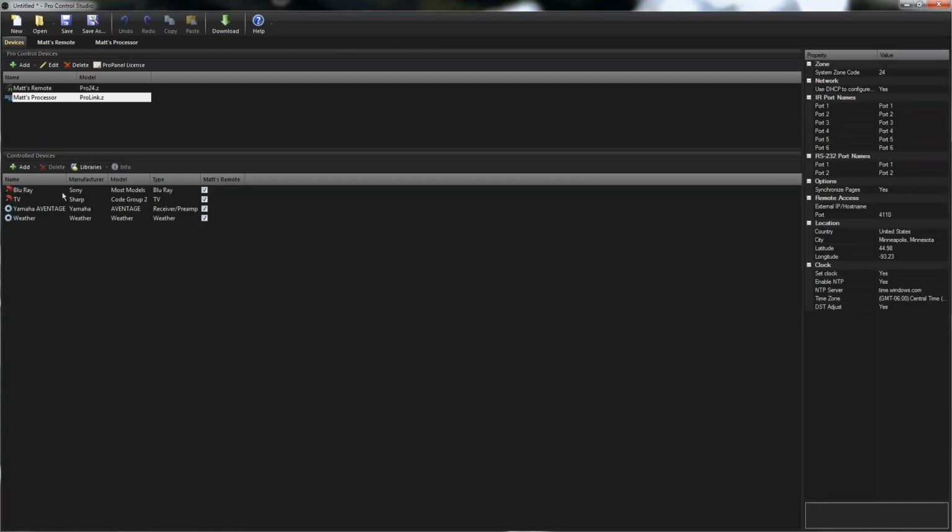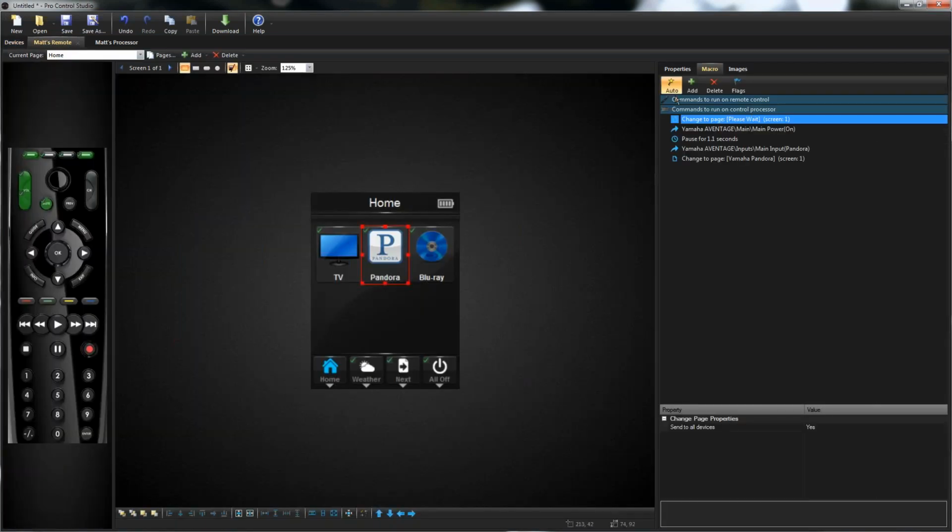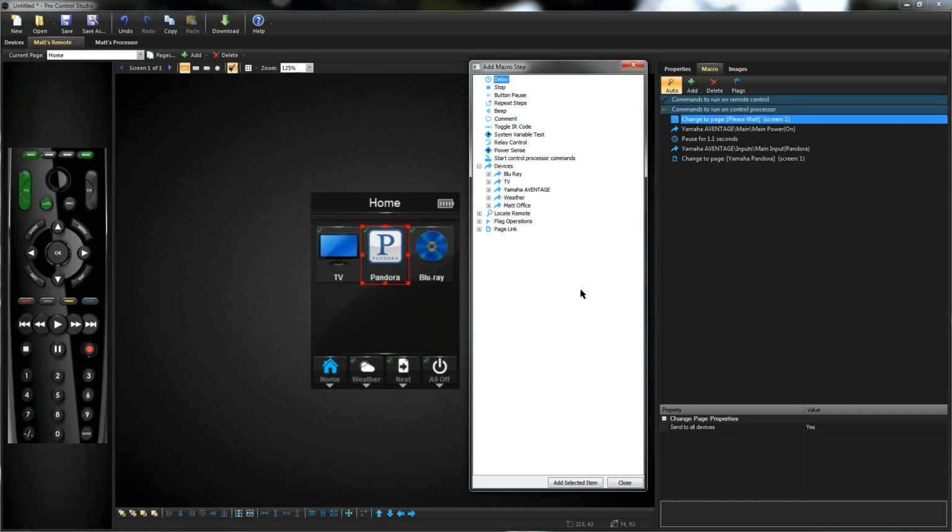Back in the system file, we work just like we used to do before. And the commands now add our office, and here's our dimmer 1, dimmer 2, here's the ramps, set level, adjust level, all the information available right here for those two devices. So I don't have to then set up my Z-Wave and usually do some node number dance and bring in information, then type in what everything is. This all imports it, dumps it right into the software for our Z-Wave devices.